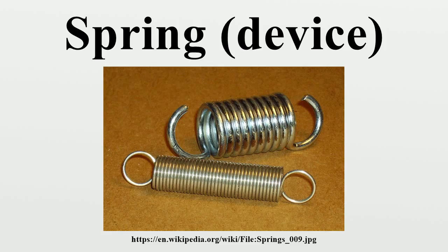Long-period pendulums enable seismometers to sense the slowest waves from earthquakes. The low-cost suspension with zero-length springs is also used in gravimeters because it is very sensitive to changes in gravity. Springs for closing doors are often made to have roughly zero length so that they will exert force even when the door is almost closed, so it will close firmly.